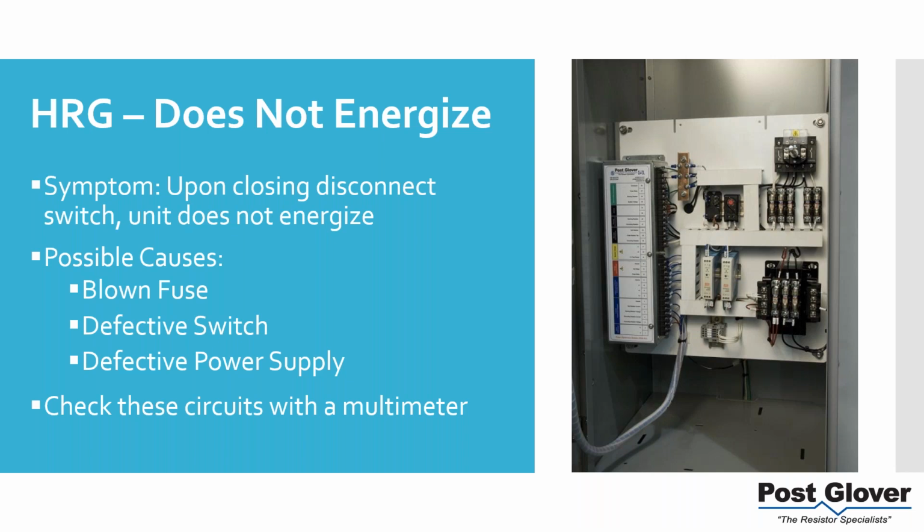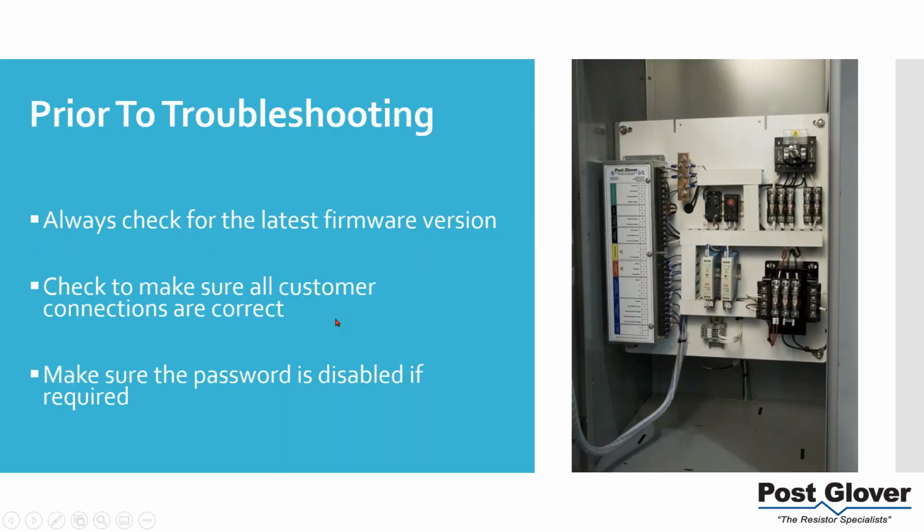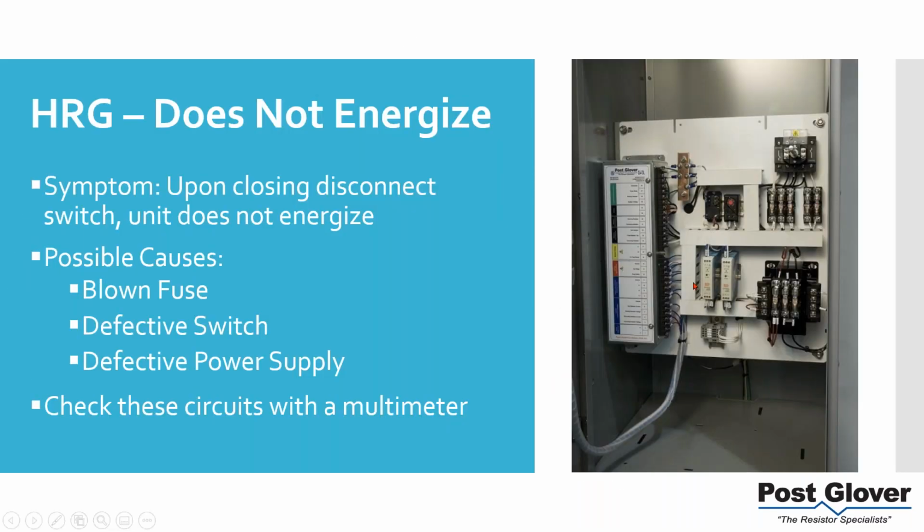I would say I've seen several times where you have a connection. In fact, let me go back and show you real quick. Oops. Oh, I can't see those here. All right. Well, there's a terminal strip on the top of the controller. That's a Phoenix terminal strip, and sometimes that can be disconnected. Typically what happens is you have somebody who opens it up, disconnects it for some reason, and then tries to put it back in, doesn't push it in all the way. That's another thing you need to look at.